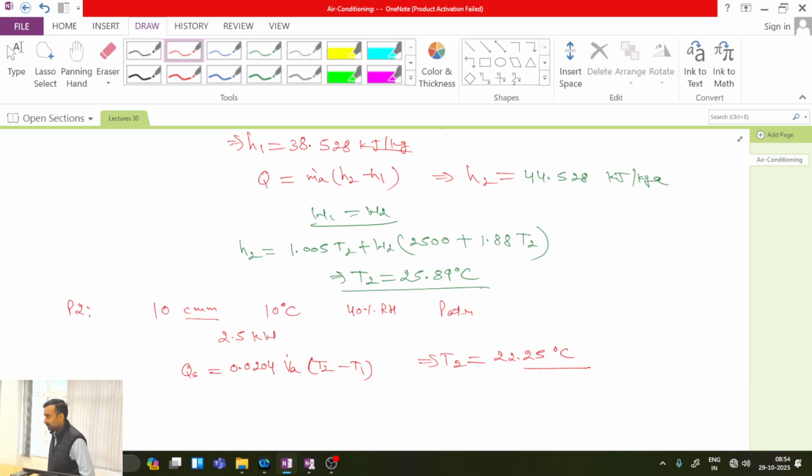Is this point clear? Because this formula is given only for STP conditions, so instead of modifying its factor and then again deriving the formula, better approach is whatever the volumetric flow rate of air I am having in CMM at the given condition, I can convert this into the conditions for which the formula is derived. Is this point clear or not?